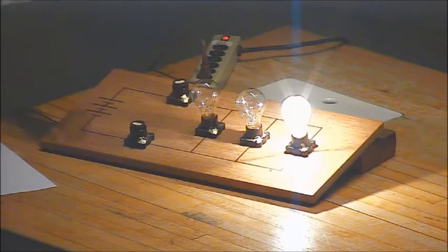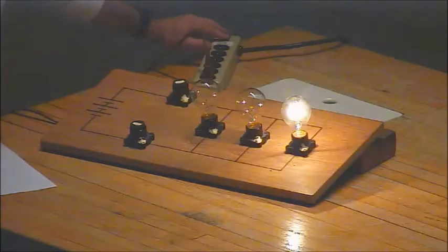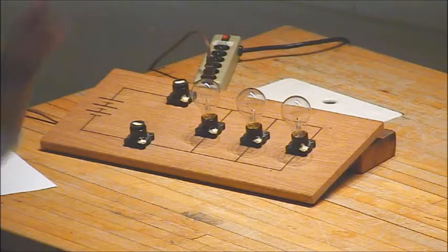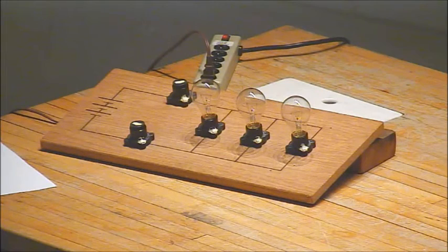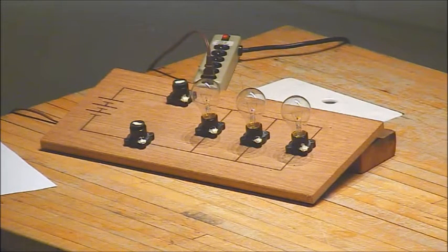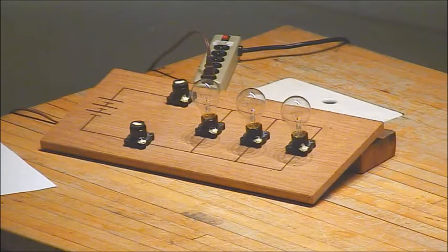Great. I think that's all we need to know right now about circuits. So that's my simplest circuit. Here I have two resistors or two light bulbs, whatever it is, two hair dryers in series, so each is seeing half the voltage drop. If those two resistors are equal, they're both going to see half. So in a 120 volt circuit, they're both going to see 60.